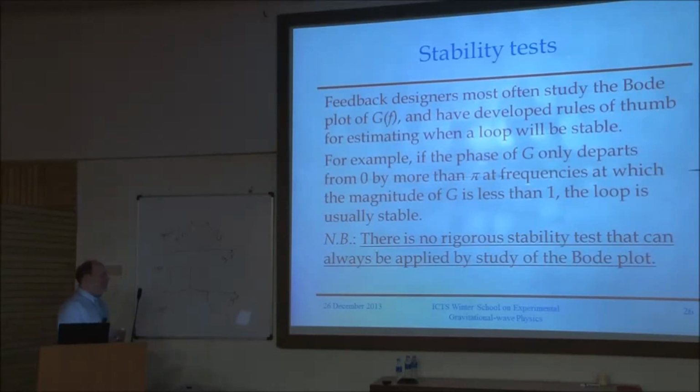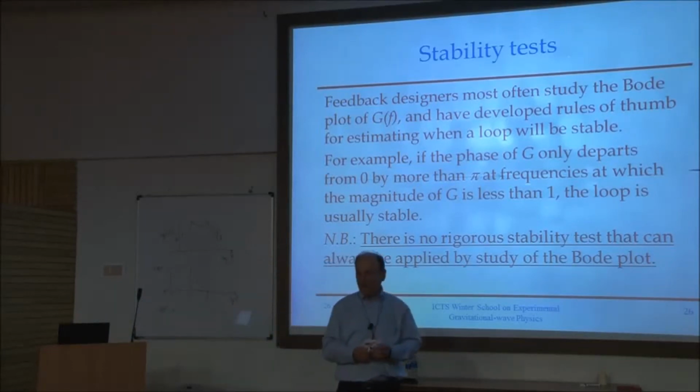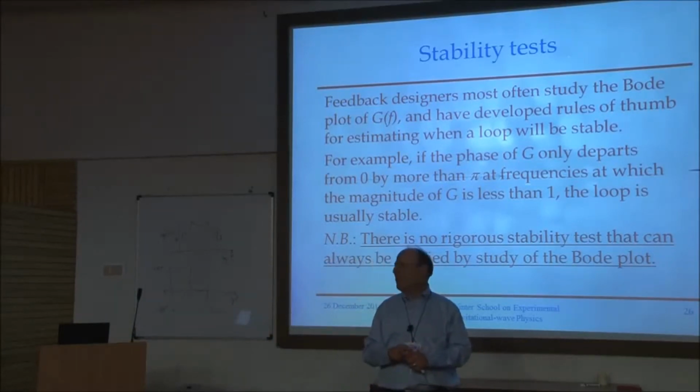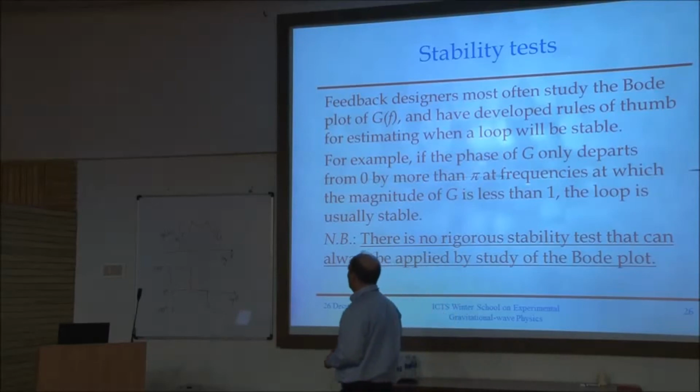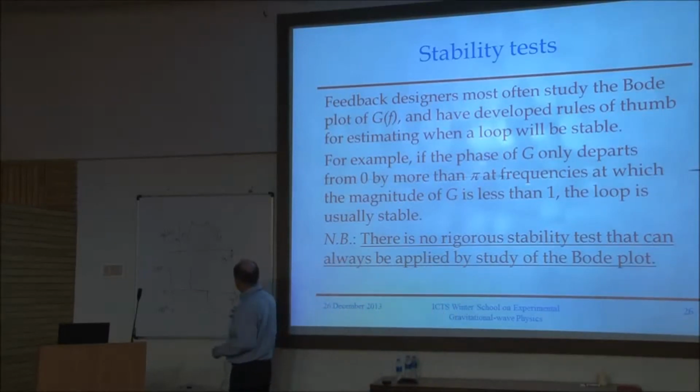Okay, Rana wanted me to be sure to say this. This is something I probably would have remembered to say in any case, but you've caught me doing something which we all do when we design servos. I caught Ali doing it too, because we all do it, and that is talking about stability looking at the Bode plot of G of f.